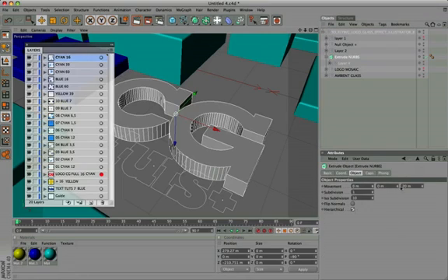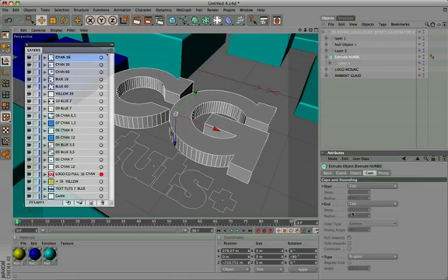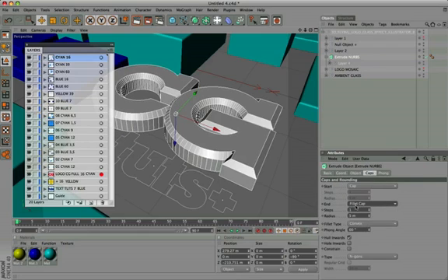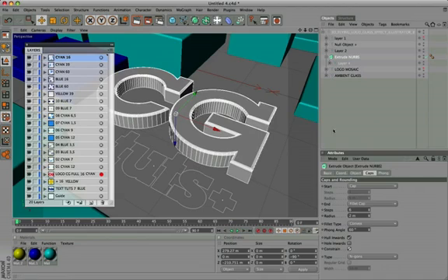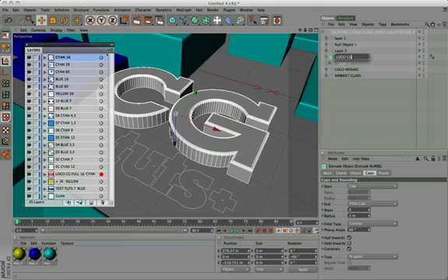Activate Hierarchical, depth minus 16. Fillet caps to end, with step value 6, radius 2. Check the constraint. Rename it Logo CG Full, and apply the cyan material.